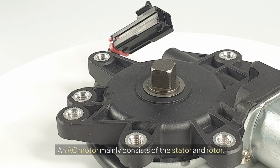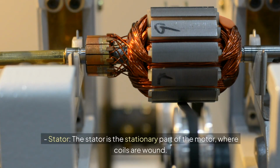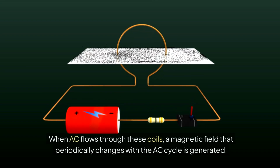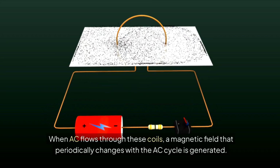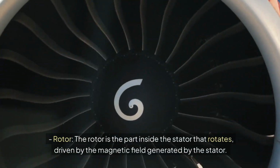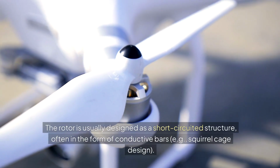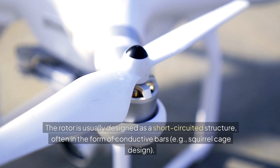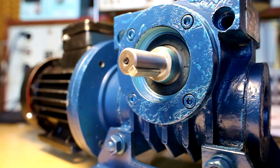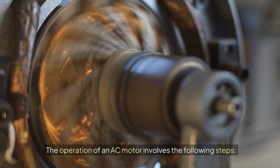1. Basic structure. An AC motor mainly consists of the stator and rotor. Stator. The stator is the stationary part of the motor, where coils are wound. When AC flows through these coils, a magnetic field that periodically changes with the AC cycle is generated. Rotor. The rotor is the part inside the stator that rotates, driven by the magnetic field generated by the stator. The rotor is usually designed as a short-circuited structure, often in the form of conductive bars, for example, squirrel cage design.